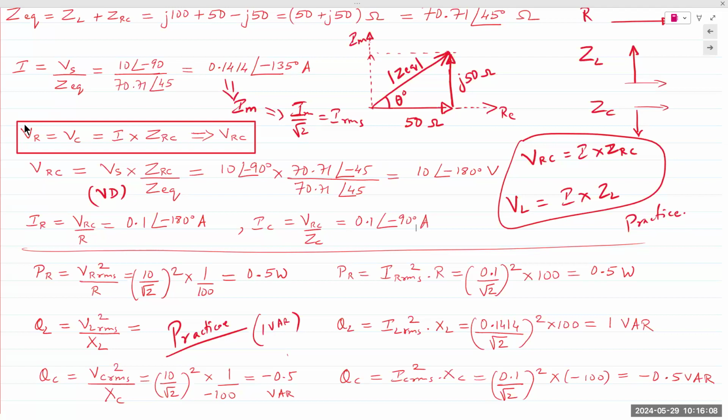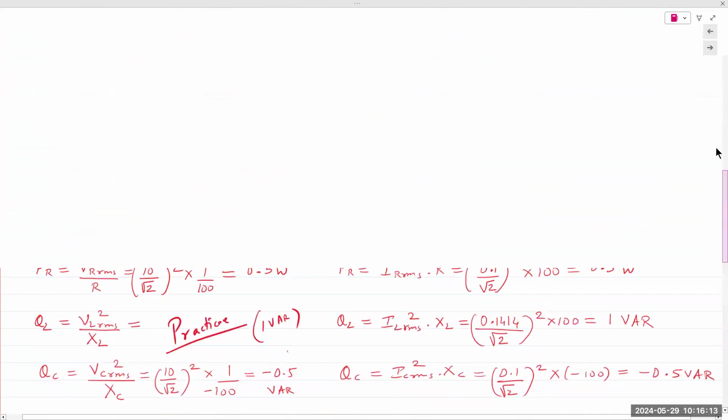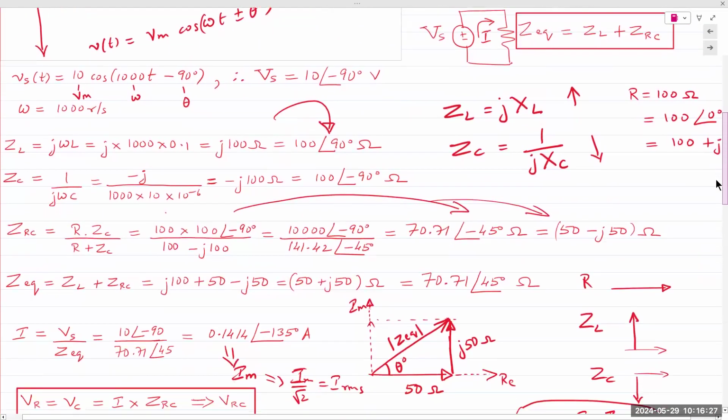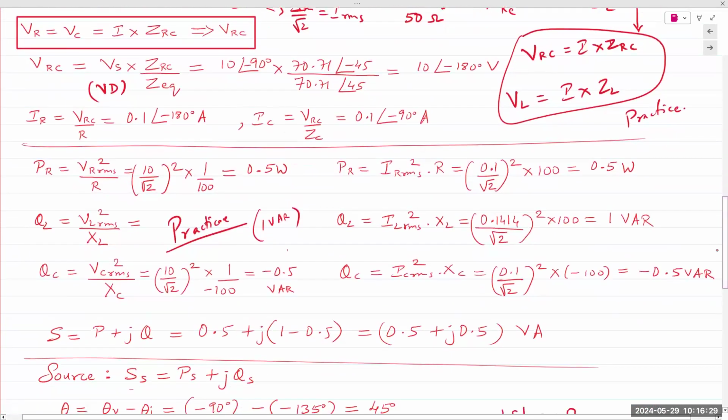Yes. So the question being asked is about the reduction of the circuit. And so the reduction of the circuit would take the same approach that we took in chapters 1 and 2. Meaning once we have the equivalent impedance diagram, we proceed as if they were all resistors. And that's why I always suggest to students, draw the diagram first and then write out the equations, and then you plug in the numbers. Once you have your approach outlined, if you start mixing up both at the same time, then it gets a little confusing. So when you're first starting out, I would always suggest derive your equations first and then plug in the numbers.